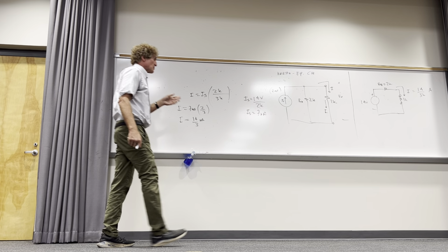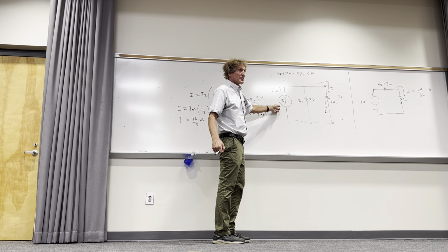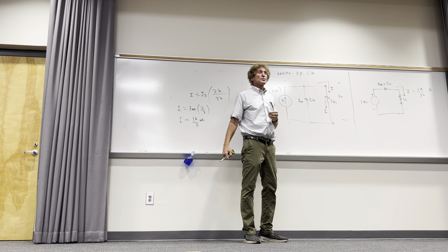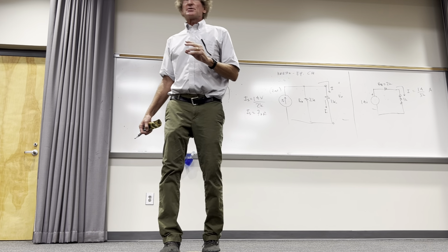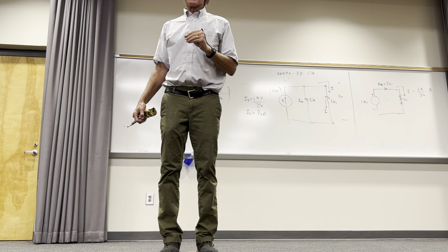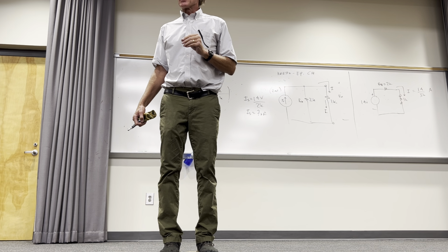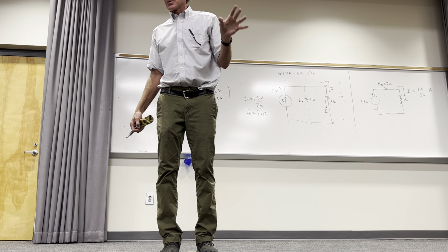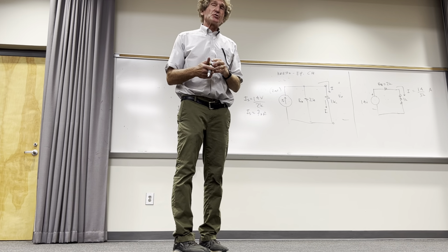If you get the short circuit current, it goes right there, then you still have to calculate the R Thevenin, it goes in parallel. Then put your real load there, and you can do it either way. Now, you don't appreciate the significance of that, but you'll see in many problems, getting the short circuit current is much easier than getting the open circuit voltage. Now, I can't say that every time, but it is true. And we'll go through more of this. I'm just showing you the options.